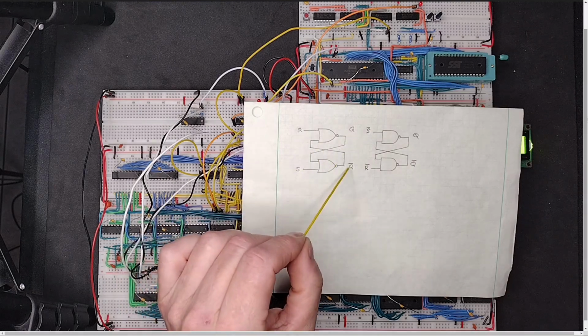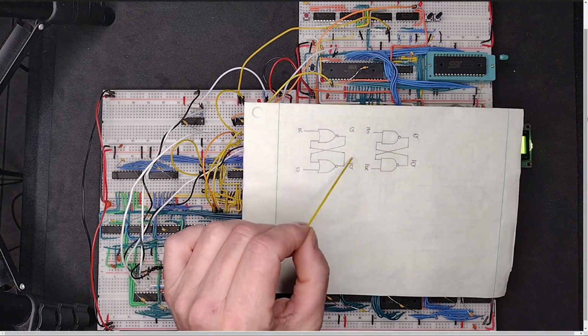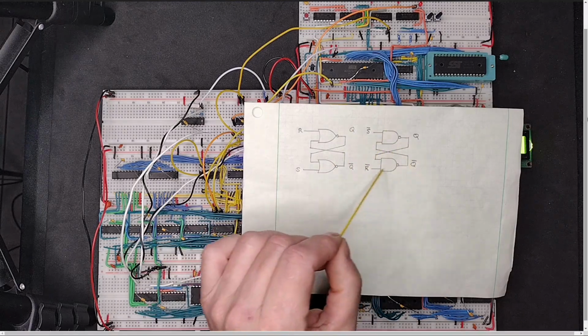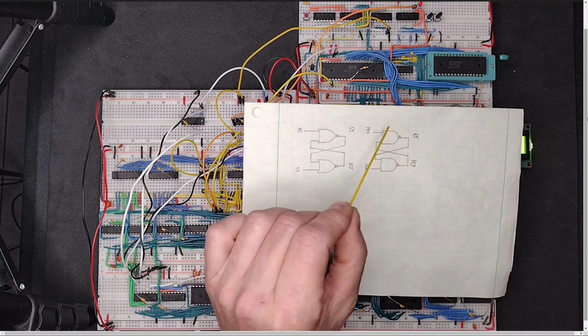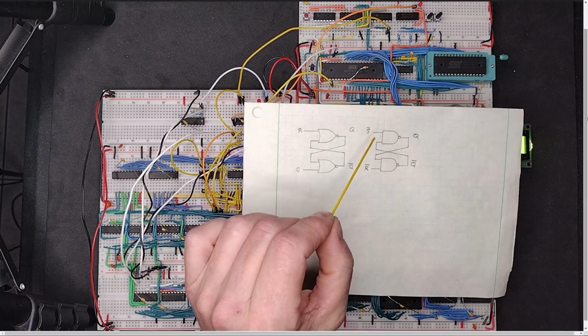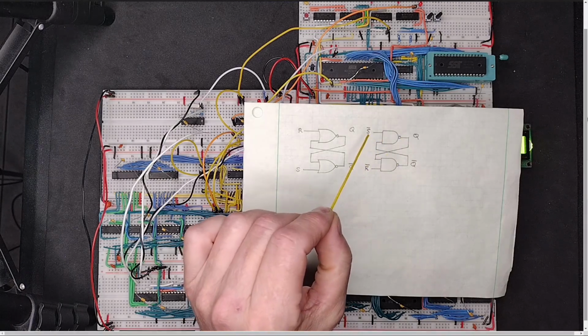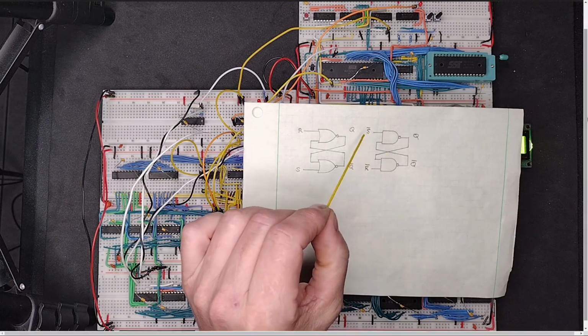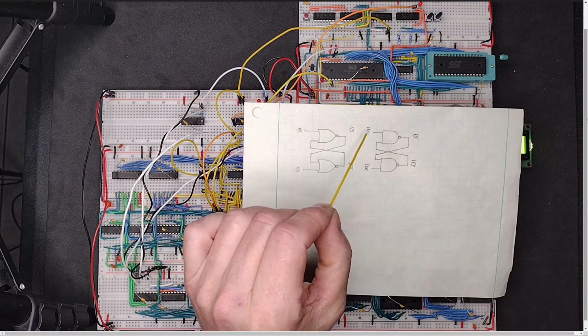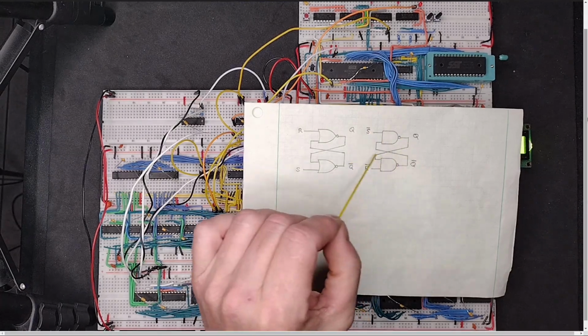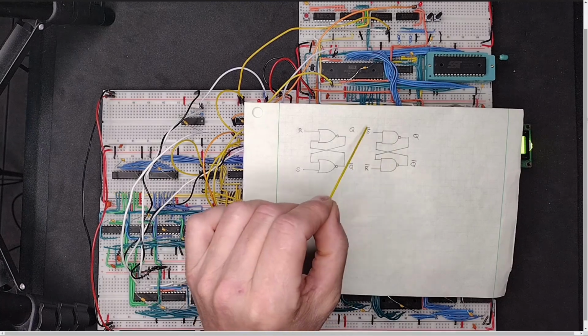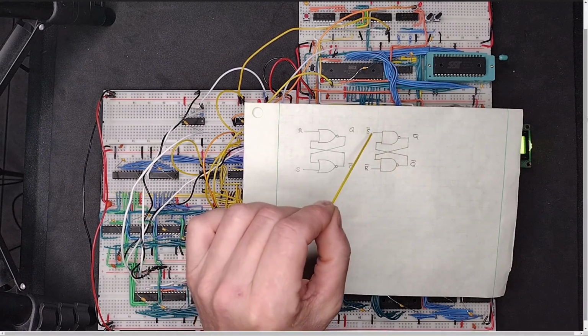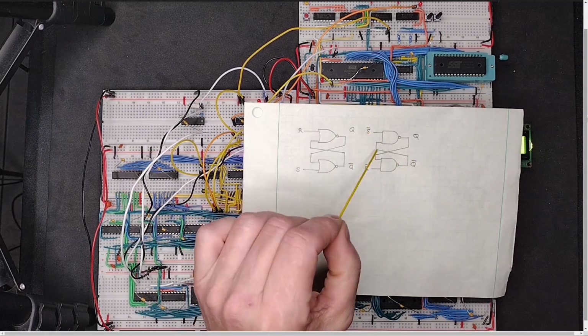You have a Q and you have a Q prime output, which is always the opposite of the Q output. And then you have the NAND gate, and I could go through the whole thing, but it works exactly the same, except instead of a positive signal, you use a negative signal. So if your signal is normally high and the interrupt is caused by a negative, then you would use this sort of gate. And I'll be using both gates in this setup, and I'll show you how. Otherwise it works the same.